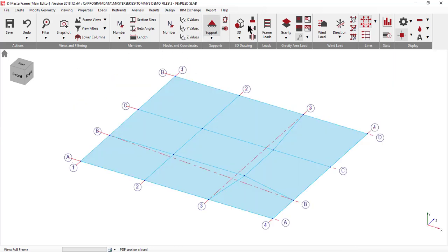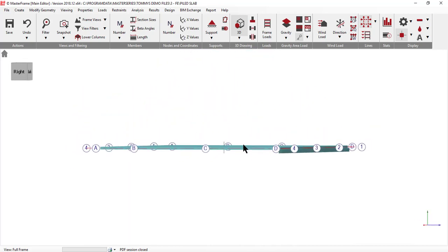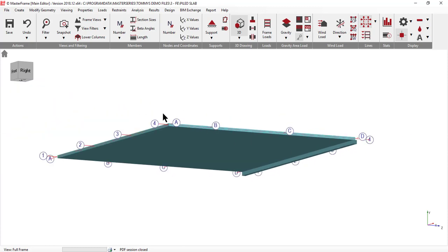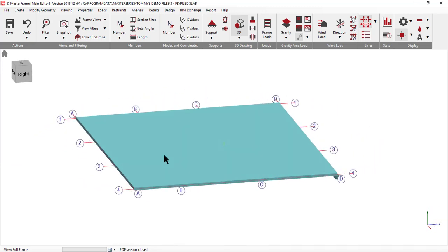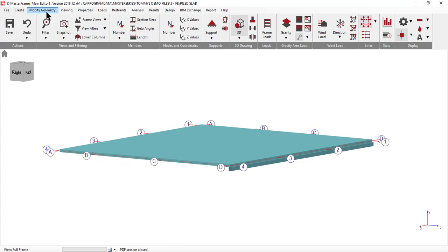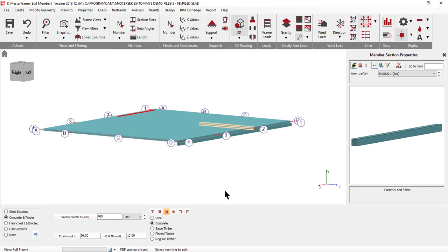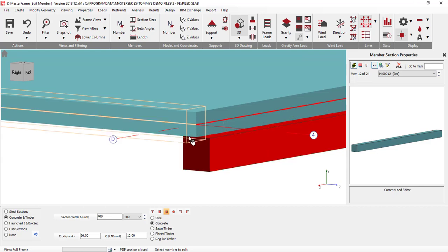So if I draw my members in 3D, I now see that I am getting these coming down and dropping down below, and that allows me to model those in the analysis and go through. But the trick here is that in the actual properties of the section for this member, I only give the value that is below the slab. So although it's defined along that centerline value, it is 400 from that point to that point.